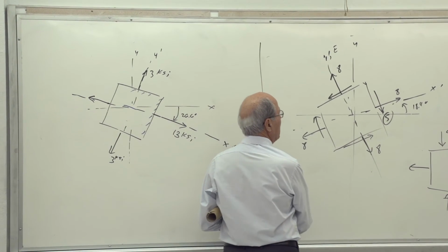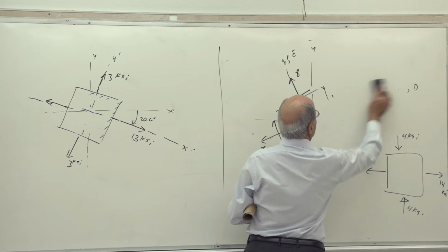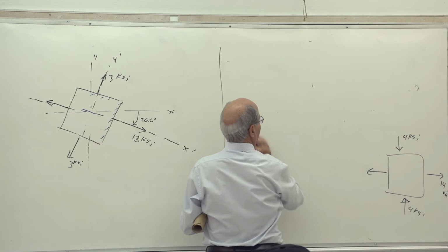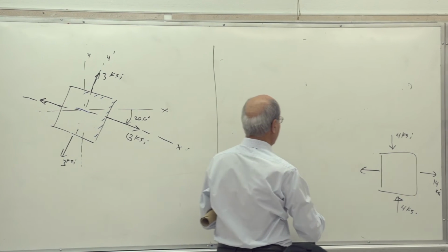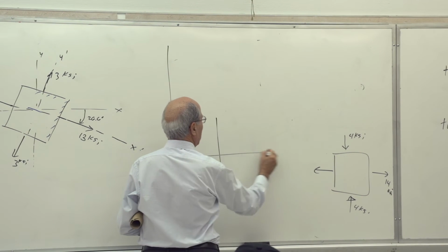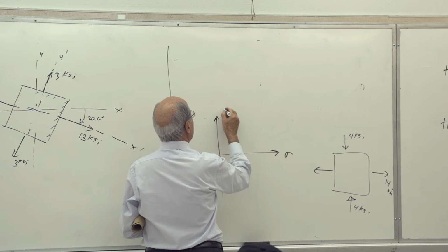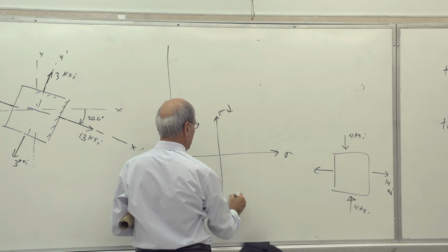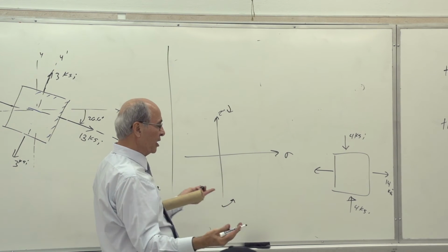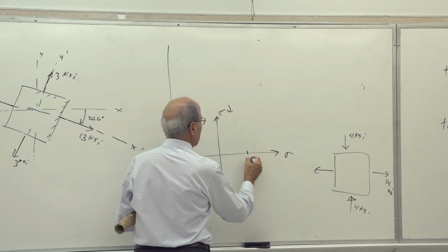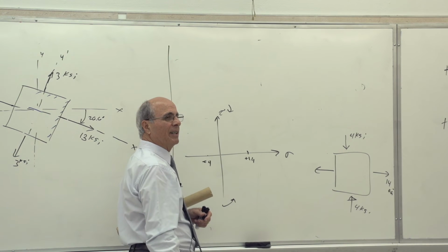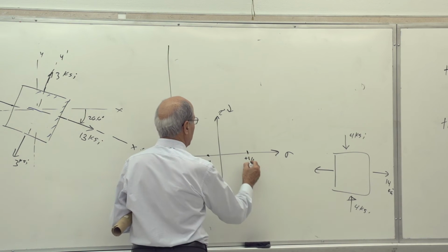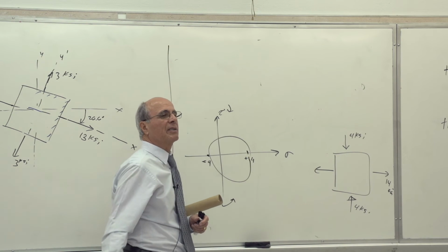As a matter of fact, can you plot a Mohr circle for that? This is A, this is B already, guys. See, this is as simple as that. Therefore, if this is sigma, this is tau. We should always remember that arrow. There is no shear here, so I go here plus 14, and I go here minus 4. Correct? And these are my 2 principal stresses. This is my circle.